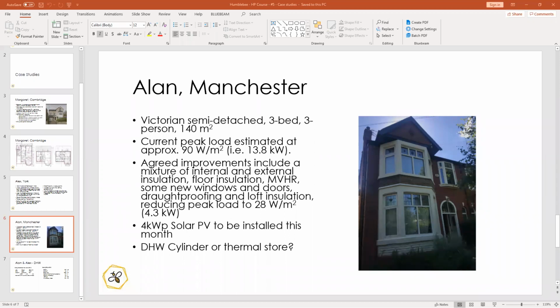I'm not against them at all. It's just my logical thinking is, obviously the hot water part is at the top where the hot water coil or plate is, and the cooler part is at the bottom, which is where you want to take your low temperature heating circuit from potentially, but the heat pump is still having to potentially meet that high target temperature to maintain that load at the top. So I need to actually get hold of one day and run a system and play with it.